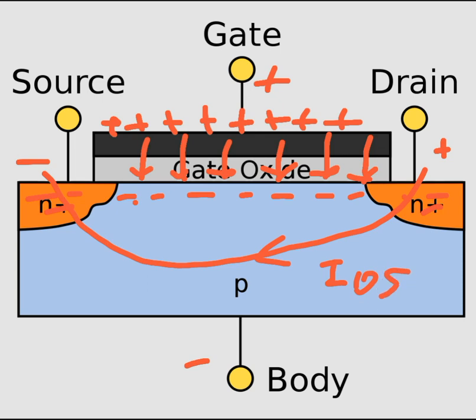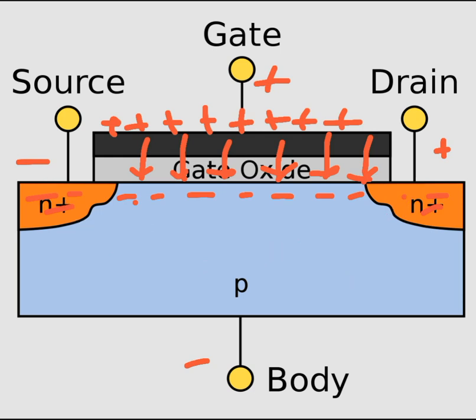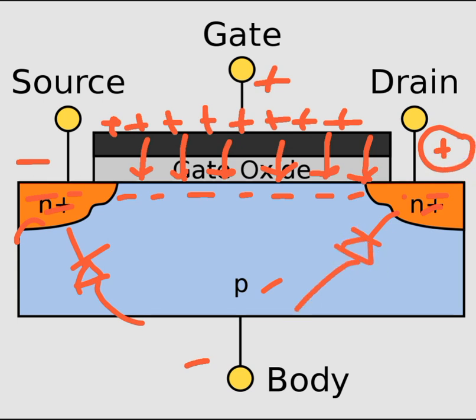So on the other hand, when you have such condition, what about the diode conditions? Let's have a look at the diode. So this is a p-type semiconductor and this is n-type semiconductor. So the n is connected to the positive and the p is connected to the negative. So this diode has a less possibility of getting forward bias. It will not get forward bias, which is advantageous. Similarly, this is connected to the positive right here, and the anode of this diode is connected to the negative. So this is completely a reverse bias diode. So the junction diodes are not getting forward bias.